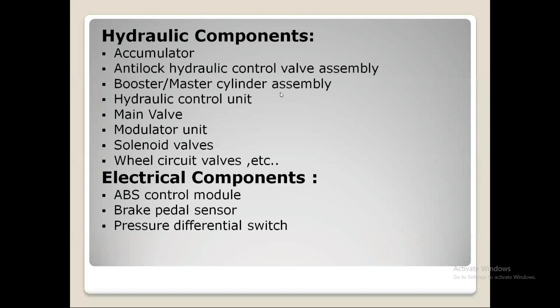This is one of the main components. And as we know, there's a brake pedal sensor. Obviously, it should be there. The anti-lock brake pedal sensor is normally closed. When the brake pedal exceeds the threshold during an anti-lock stop, the anti-lock brake control module senses that the anti-lock pedal sensor switch is open and grounds the pump motor relay coil.